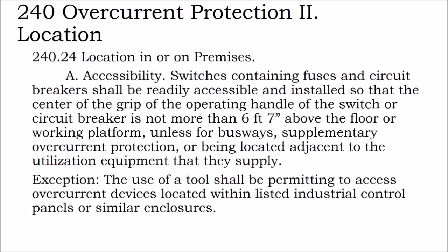Location in or on premises, the accessibility. Switches containing fuses and circuit breakers shall be readily accessible. So, we have that combiner box on the rooftop, and your inspector may say, well, that needs to be readily accessible.